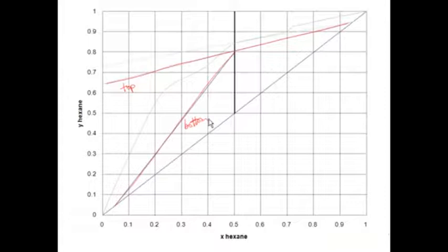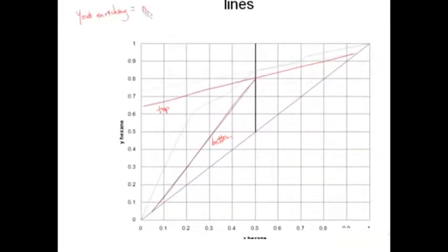So our limits of integration, y out enriching equals 0.95. So that's up here. Y in enriching equals y out stripping equals 0.802 here, and then y in stripping equals, because it's a partial reboiler, 0.15.